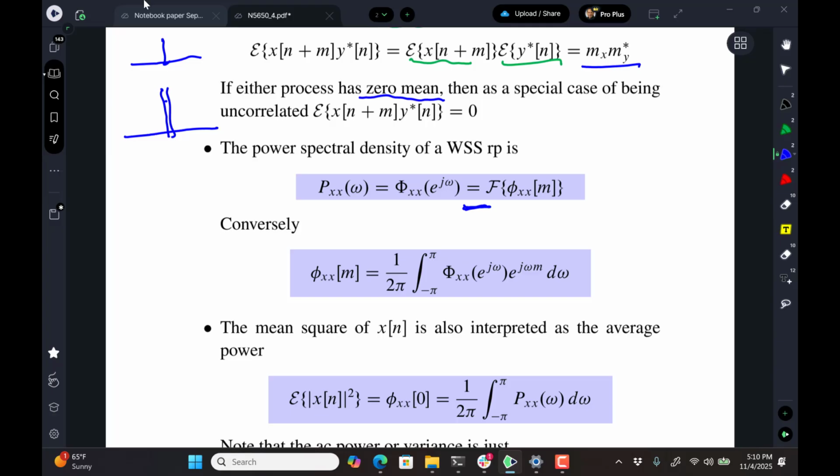And a significant thing here, which I'll elaborate on a little bit more, is the power spectral density can be estimated in the time domain as well, and we're going to be exploring that. The function simple SA, or simple spectrum analyzer, is exactly designed to find the power spectrum of a random process. It finds the power spectrum of a deterministic signal too, but it's especially powerful for random processes. And if you inverse Fourier transform the power spectral density, you get back the autocorrelation function.